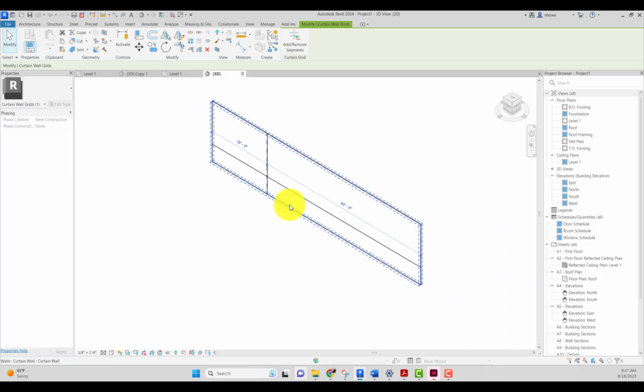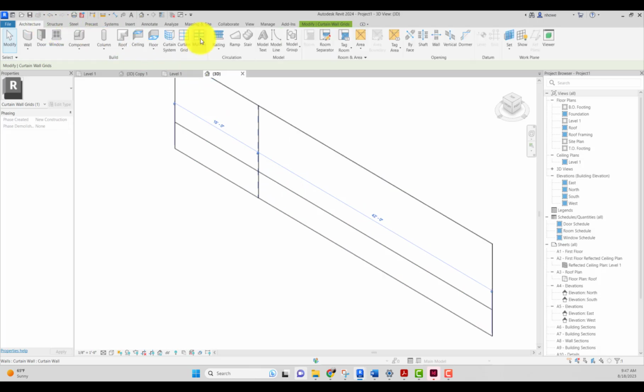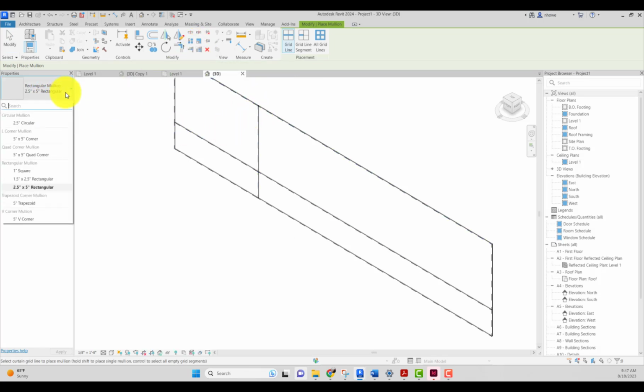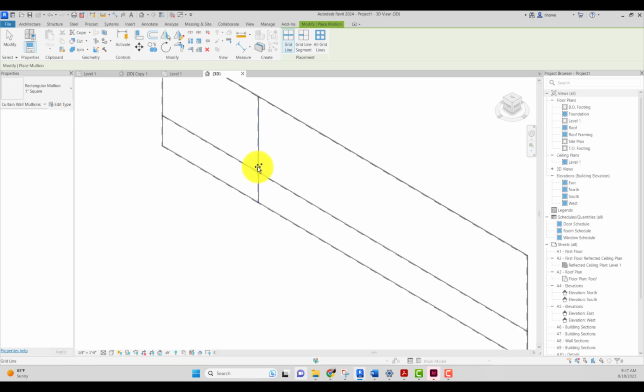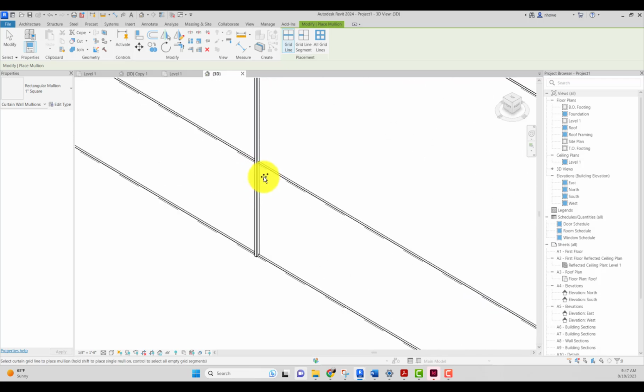So this can be a great way, if you're designing the curtain wall system, to really align it with other design moves that you've made. And we'll keep going. Now, curtain wall mullions, this is where if I'm doing this kind of custom piece, then I start to select various profiles of mullions. So the mullions are the metal dividers that encapsulate the glass itself.